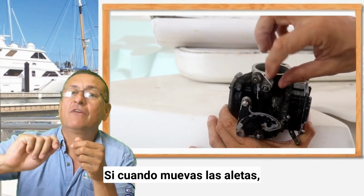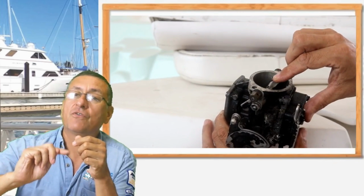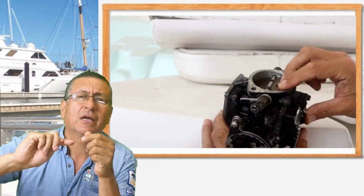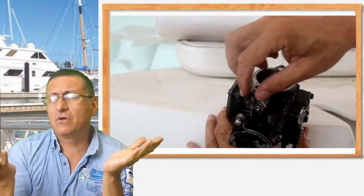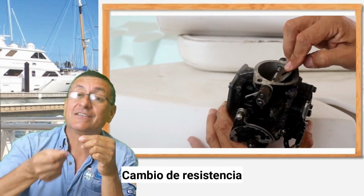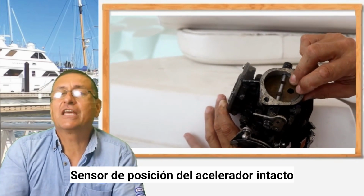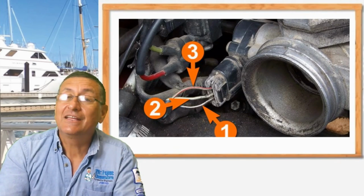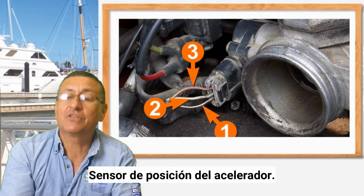If when you move the flap, the resistance change from 200 ohms until 1.2 kilo ohms, depend of the manufacturer. If the resistance change, it's because the throttle position sensor is in good condition. Okay, this is one sensor, the throttle position sensor.